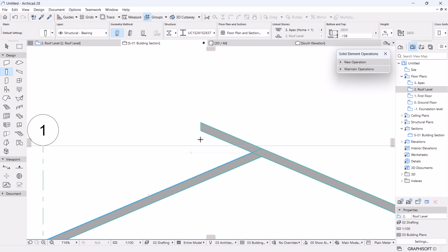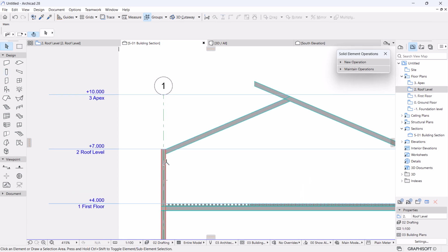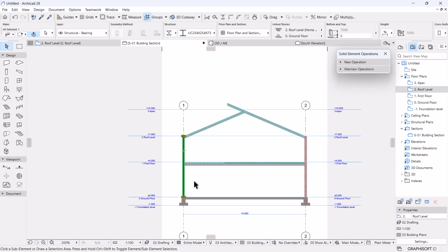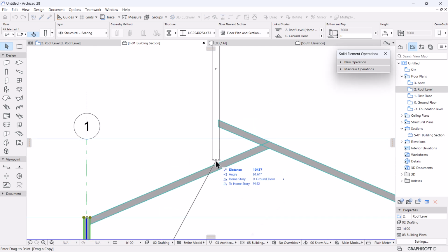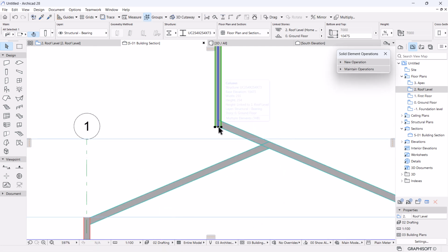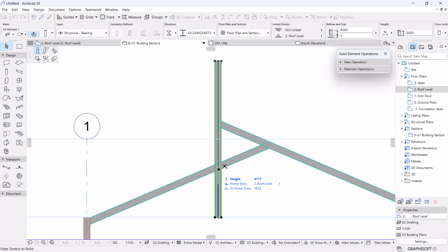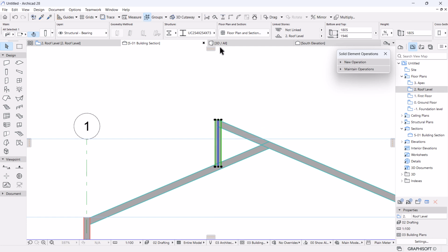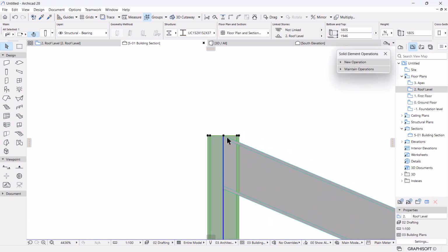Could I draw a column here? No. So I thought I'll do that. I'm going to Control Shift T and carry the copy of this to there. Set this to be on the roof level, and 0, which is the base offset. I'm going to stretch the height all the way to the midpoint of that, and the same with that one. Let's change the size to 152.